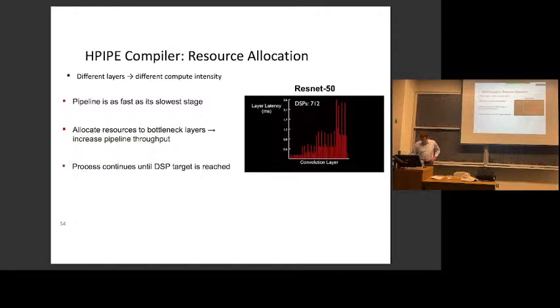So if we just hook these up in a pipeline, this is what's going to determine our speed, right? It's the time to get through those later layers. Whoops, every time I draw on the slides, it wants to keep going. Okay, so initially HPipe just makes every PE have the minimum parallelism settings, sees how much resources have I used, and if that's too much, we're in trouble.